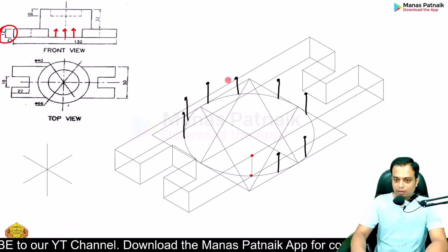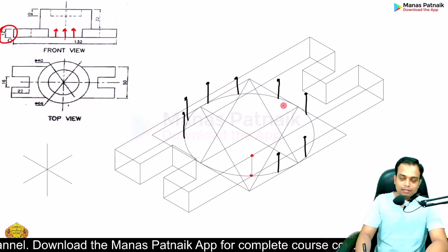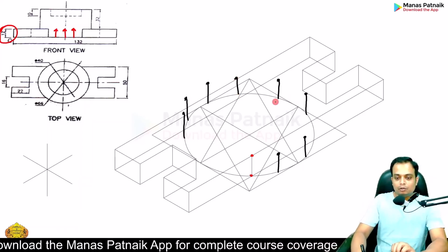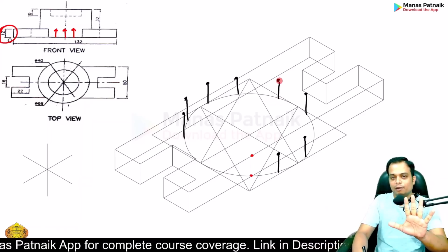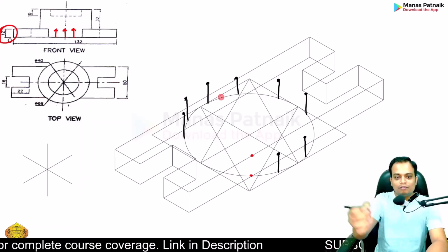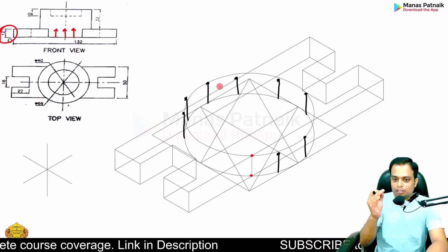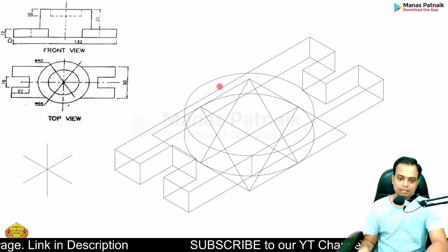And when you connect all of these points, you have to do it very professionally. You don't need to make these lines. Rather, I would suggest you keep your mini drafter absolutely vertical, and then at a height of 12 millimeters, make a point. Keep on making points. Once you have sufficient points, connect all of these dots with the help of a smooth curve like this. Beautiful, isn't it?